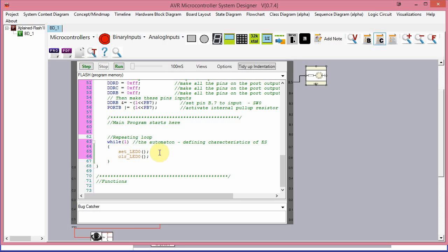Now that really is just the fact that people are so slow compared to computers, even a little microcontroller that runs at only 16 megahertz. This instruction will happen in 1/16th of a millionth of a second. So the two of them will happen in 2/16ths of a millionth of a second. We will not see the LED flashing. We need to pause this thing. And there's this little function we have access to called delay. And so we're going to delay it for 1/4 of a second.